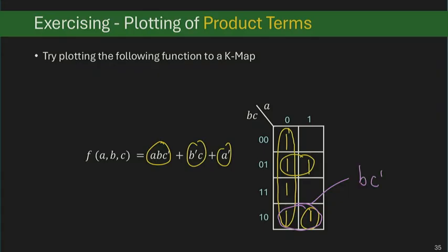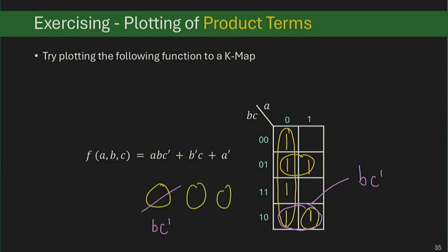Therefore, we can replace AB prime C prime and ABC prime with BC prime. That is also something you should be able to realize from Boolean algebra. Between A and this ABC prime, A is a term that can be eliminated by applying term elimination. Essentially, that's the very same optimization that you can get from the Karnaugh map directly.